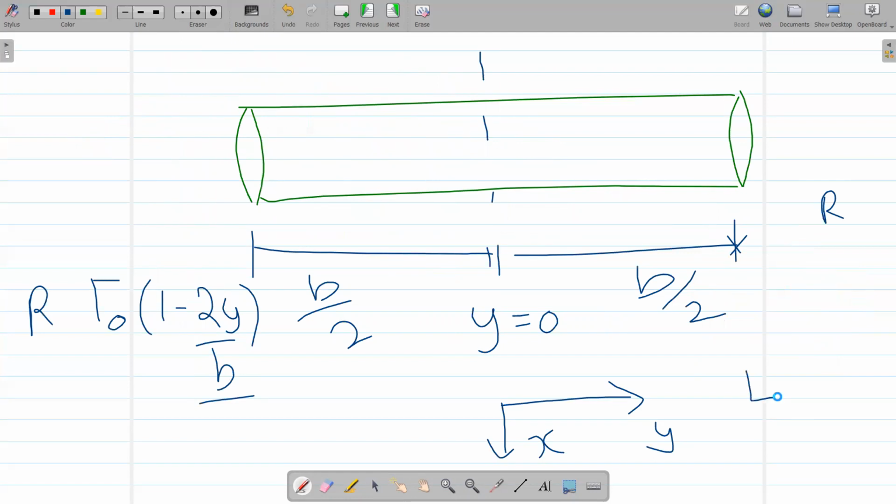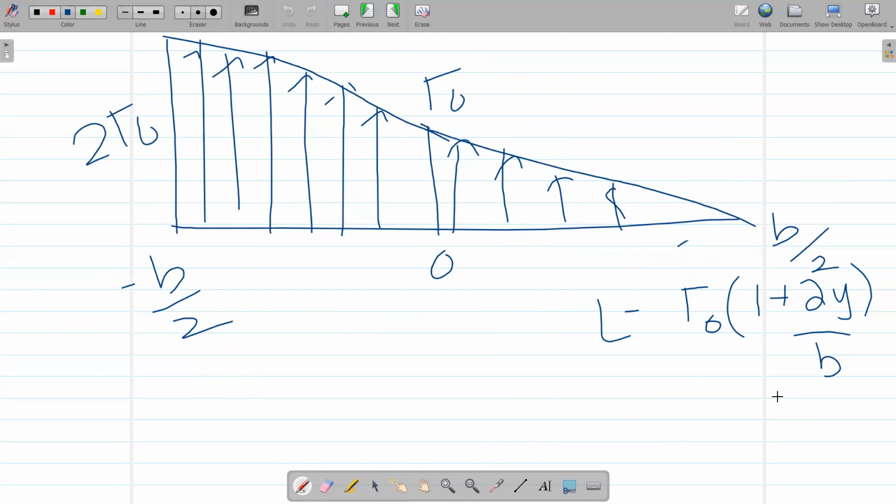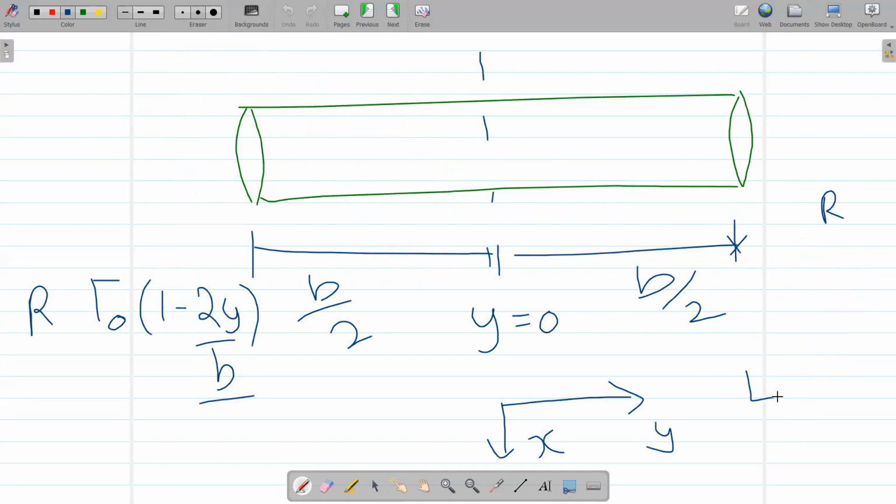So now we know that, with the help of gamma, you'll be able to find the lift at any given section. So let's say I take a very, very small strip of this wing, and let the small strip be of length dy. The lift per unit length over this small region is defined according to the Kutta-Joukowski theorem.